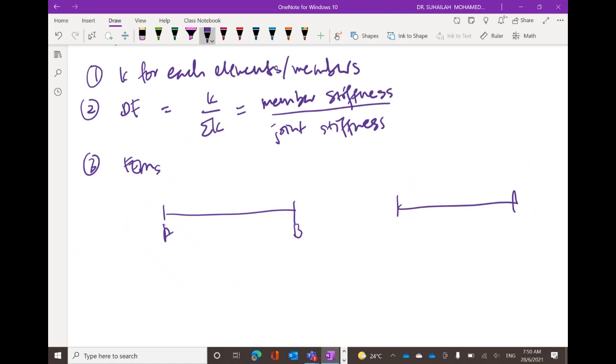The appendix is given in chapter number 2, or you can also refer to the appendix in the back page of the textbook. Actually, there are formulas for fixed end moment based on far end condition. However, we can also solve all fixed end moments by first assuming both ends are fixed.